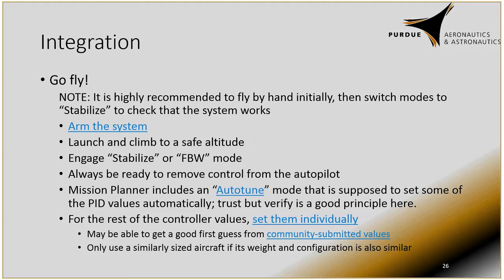So launch it, climb to safe altitude, engage your stabilizer, fly-by-wire mode. Make sure that it flies steadily. That's the big thing, right? Always be prepared to take control away from it.